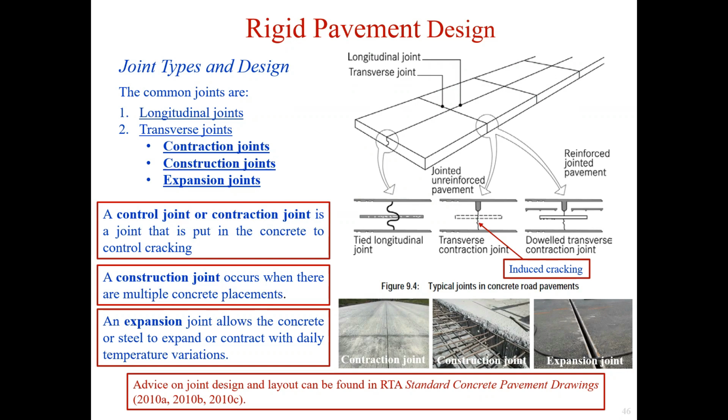The contraction joint, or control joint, is mainly used to control cracking. These joints do not go all the way through the thickness of the slab, but rather about a quarter of the depth. They serve only as a weak place in the concrete where cracks can occur and then later be sealed up. Normally, these joints do not require a load transfer device, as it can be achieved by the interlocking of aggregates. Some projects also use dowel bars to fully bond the concrete.